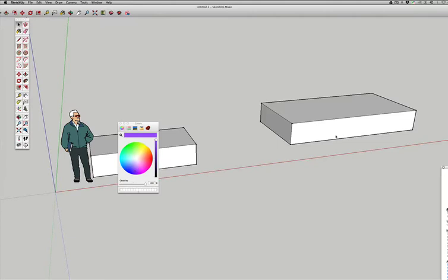If I hit R for rotate, let's go. That won't rotate. It's got to be Q. So don't use R. I'm going here in the middle, and I could drop lines in here and find the midpoint. One thing you do is with the line here, you go on the edge. See, that's a midpoint. Go all the way down here. See that light blue? That's another midpoint. Then you can go over here until you hit the midpoint. Boom, midpoint. All right? And so what I'm going to do is hit Q right there.